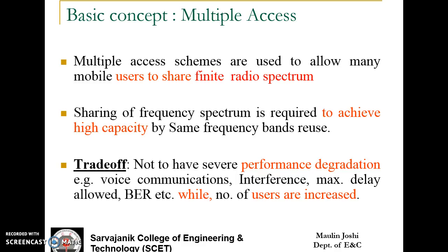Multiple access schemes are used to allow many mobile users to share the finite radio spectrum, and we know that this is scarce in nature. Sharing of the frequency spectrum is required to achieve high capacity by using the same frequency bands. At the same time, we need to understand the trade-off that performance should not get degraded in any of the applications, like voice communications, interference cases, maximum delay which has been allowed, and bit error rate, while we try to make the number of users more and more.